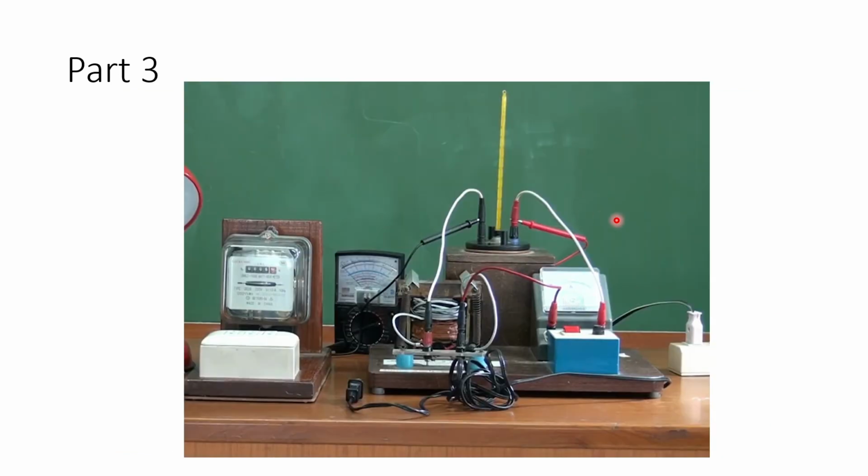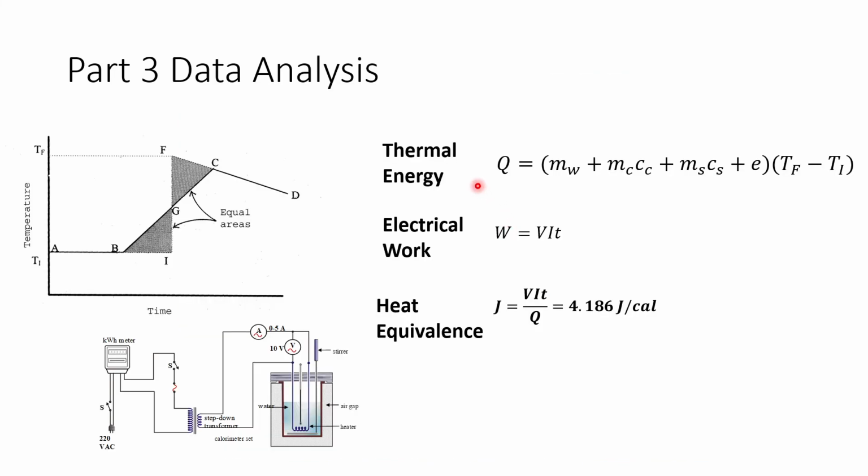All right. On the last part, you're going to be using a step down transformer, and then use that winding to create the current that goes into the water heater inside of a calorimeter, as I mentioned earlier in the diagram. From there, you can measure the power and measure the heat that goes in, and you can measure the thermal energy by using a thermometer. Technically, what you need to do is make a calculation. Based on this, you get the electrical energy in, and then you get the thermal energy out.